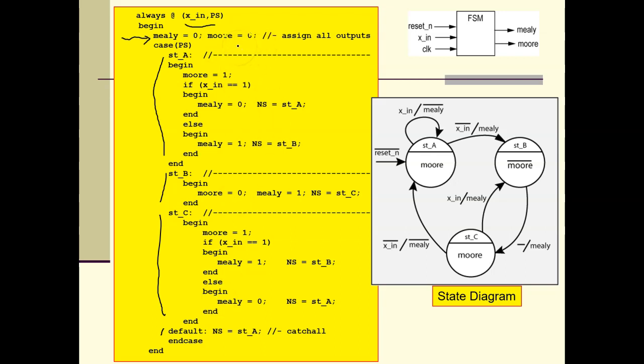If it generates a latch, I'm in trouble. It just operates stupid, and it's hard to fix. So I'm doing everything I can to avoid a latch. Now the thing you could do instead is, I'm not sure if I do it or not, but it looks like I do it, so not a big deal. In every state, I assign Mealy and Moore values, and it looks like I do in this state machine, so not a big deal.